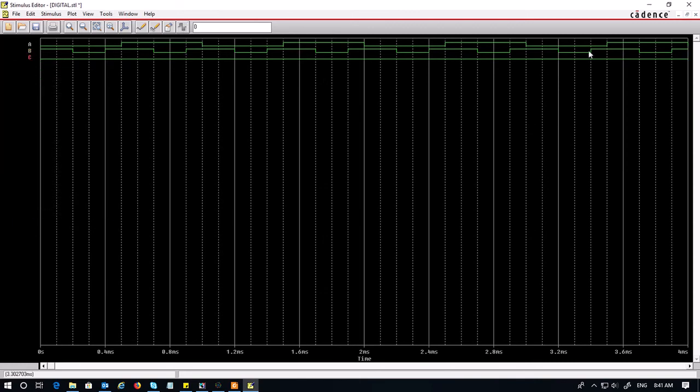So right now the whole signal is a 0 signal. How do you change levels? To change levels, you see this high level and low level button right here where my mouse is. Press this button and observe that the mouse becomes a pencil. If you take this pencil and put it anywhere on the signal C that you want to change into random ones and zeros, and click it, it's going to change the level at that point.